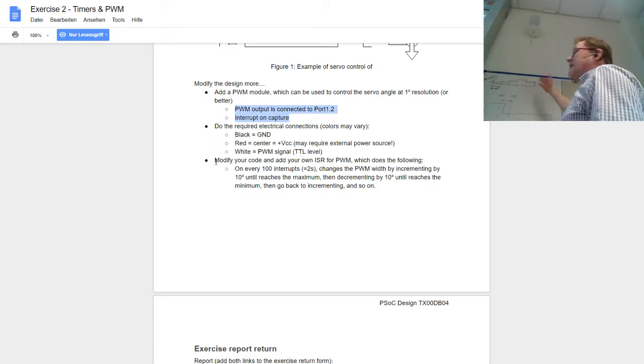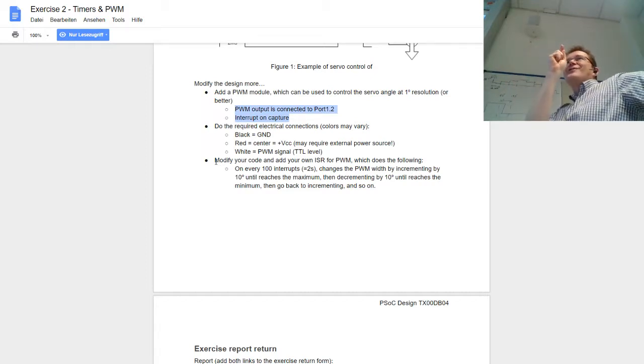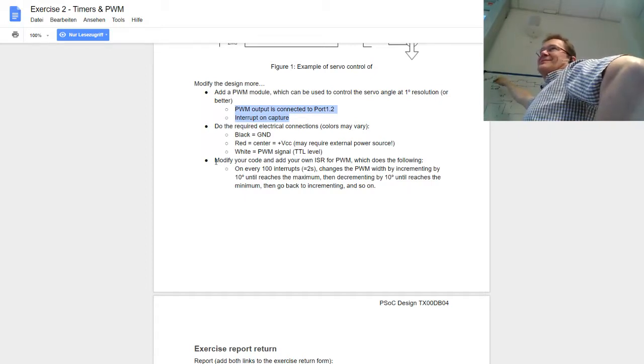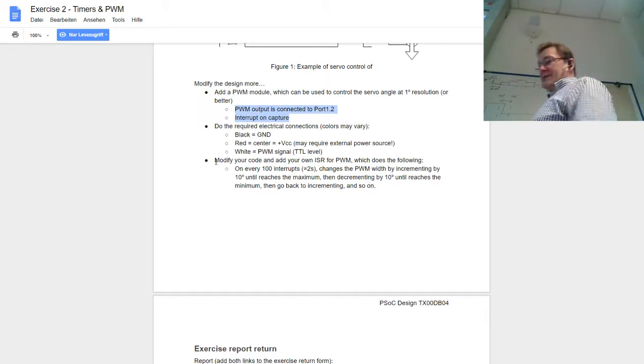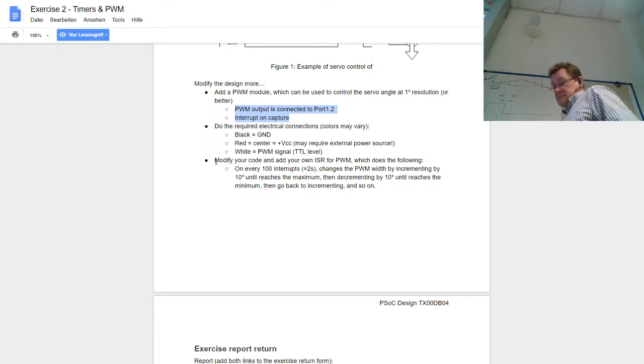And another thing, you can then think of, okay, there was 2 seconds on 100 counts, but how about just making a gradual change? So this is basic linear interpolation. You just make this one shorter and also the step size smaller. That's the way you can do smoother, controlled movement, like that, following a line.